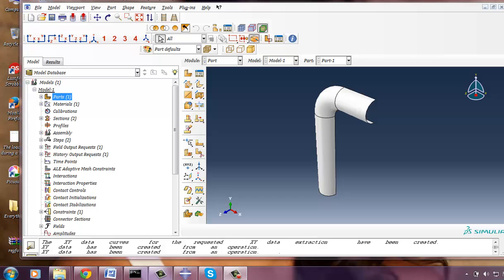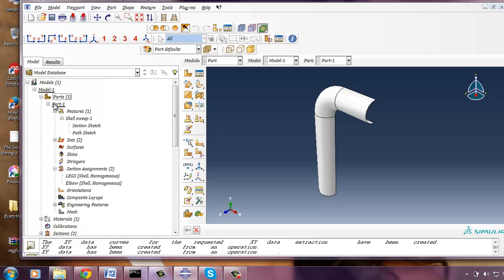So I'm going to use the Riks algorithm method, and it is generally used to predict unstable geometrically nonlinear collapse of a structure. It can include nonlinear material and boundary conditions too. This method is also used for cases where the loading is proportional. So I'm going to create parts. I already created all the parts and steps, but I will go through it and make you understand also.